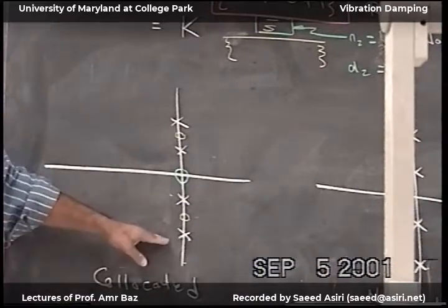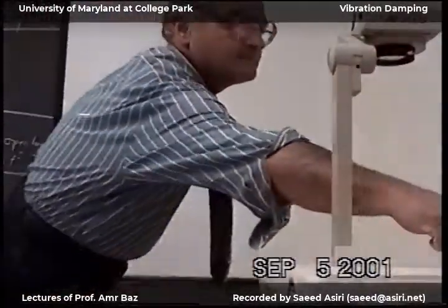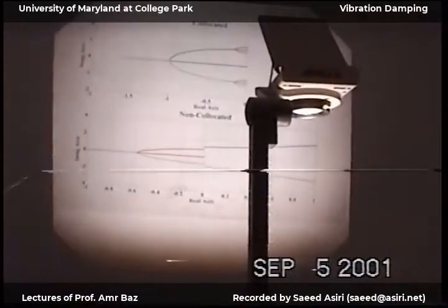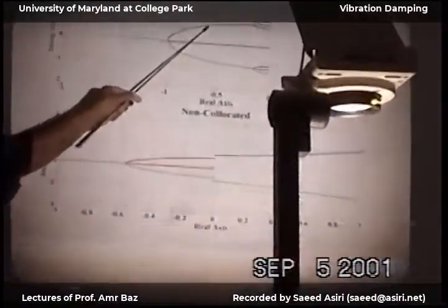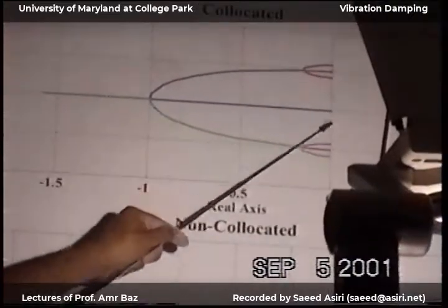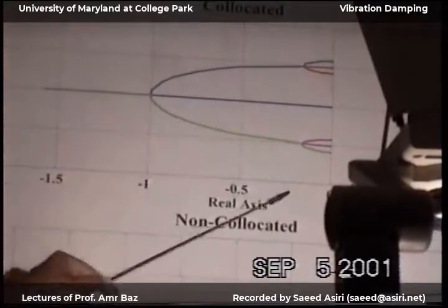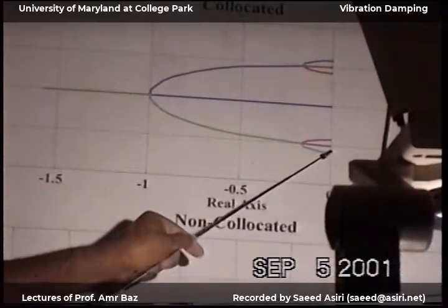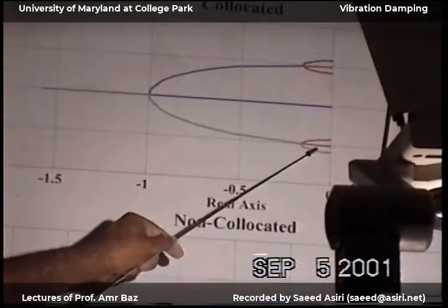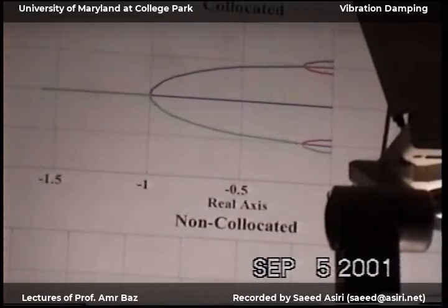So I'll have 3 branches, very clear. So if you look here, we have the blue branch, the red branch, and this branch, and then I have one more from a pole, and it's trying to find the 0, cannot find it, just keep looking for it till infinity. Okay? So this is trying to find the zero at infinity.